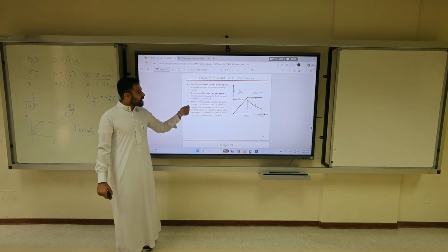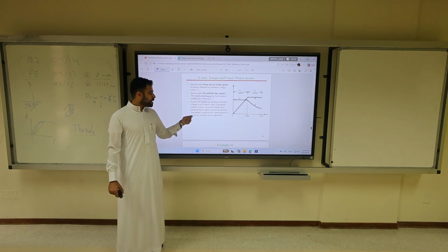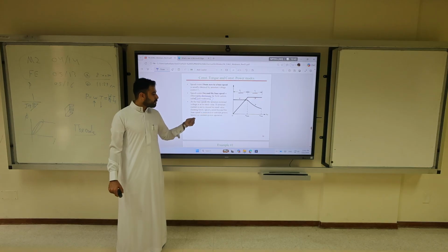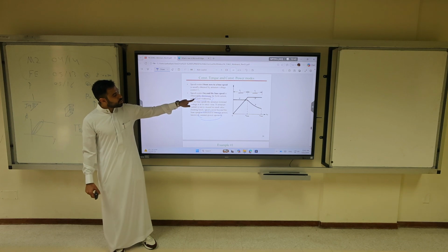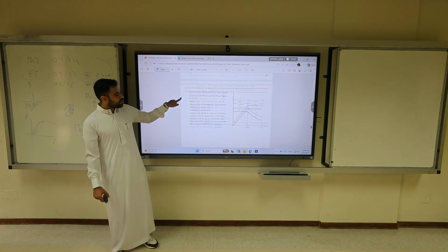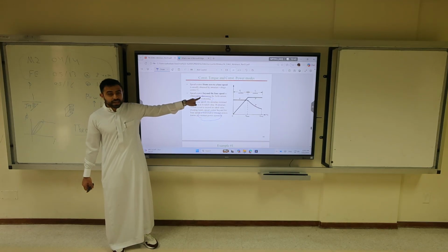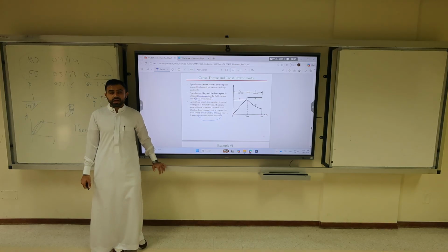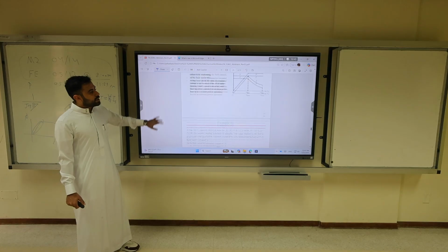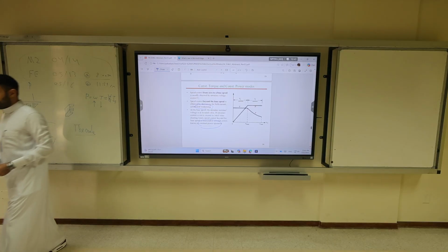At the base speed, the armature terminal voltage is at rated value. If armature current is not to exceed the rated value, the heating limit, speed control beyond base speed is restricted to constant power, known as the constant power operation, also known as field weakening. So field weakening and constant power are the same thing, two names are used. Okay? This is only the traditional approach of controlling the machine.